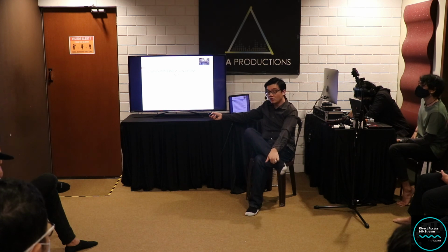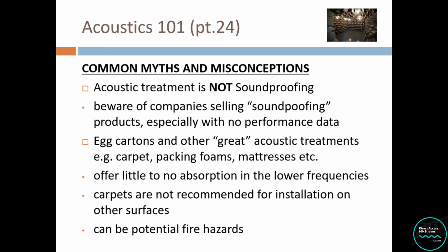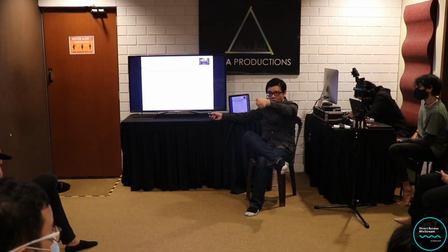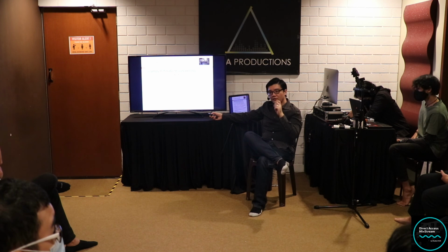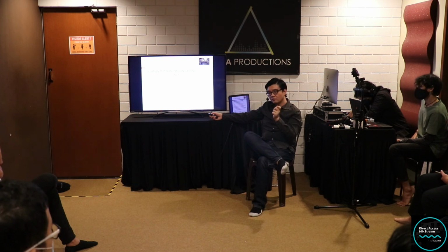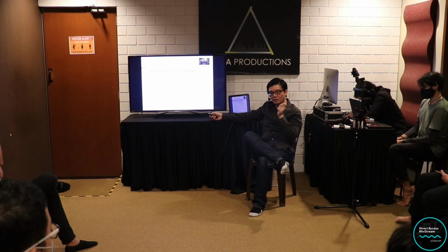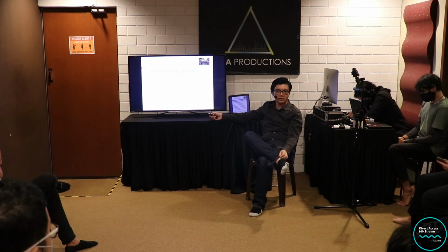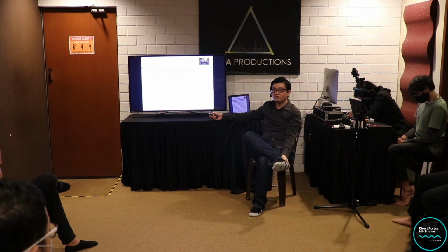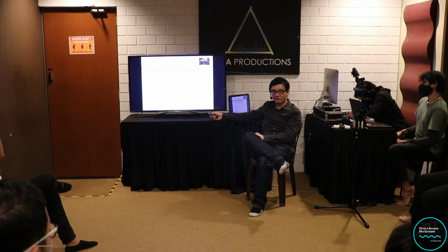Another major issue that a lot of people forget: these are potential fire hazards. Proper acoustic products, like for example, I think these are all mostly Auralex panels, are already fire treated, or made with material that has a fire rating. I won't go into details, but you go onto YouTube and look at some of the videos, especially the fire department, bomba, demonstrations. They will show you how fast a common household material, like a curtain or a bed or mattress, will catch fire just from a single spark. Very fast. It's very scary, I tell you.